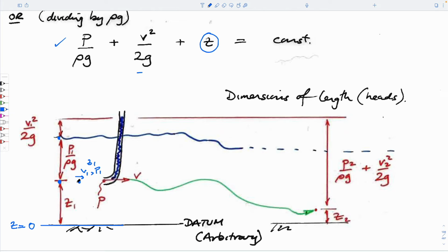And so you don't necessarily know what this pressure is, well, actually you probably do know what this pressure is. If you drew this out, it turns out you probably don't know this yet. But if you looked at the pressure distribution at this point, it would look something like this. Just because the fluid is moving at some velocity below a free surface, this curve here is still equal to dp dz is equal to minus unit weight. So it's still this linear form.